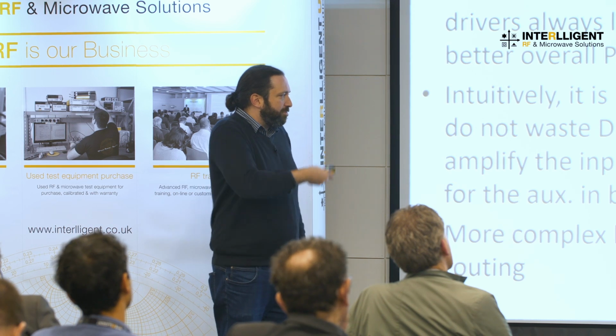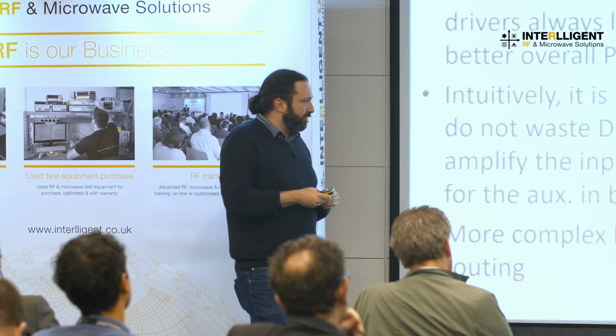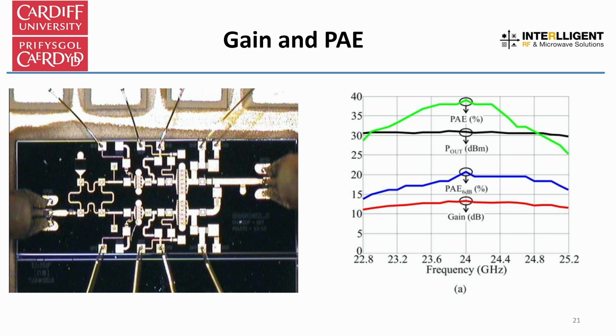So we came up with this. This was a quite nice thing. We got it published. We were happy with it. So this was a TriQuint process, was the power amp. They had gallium arsenide, and this design was really targeting point-to-point backhaul at the time. So we got some decent results. The PAE was around 20% in the best case average, back off, which was close to the state of the art. Otherwise, you wouldn't go into the transactions.